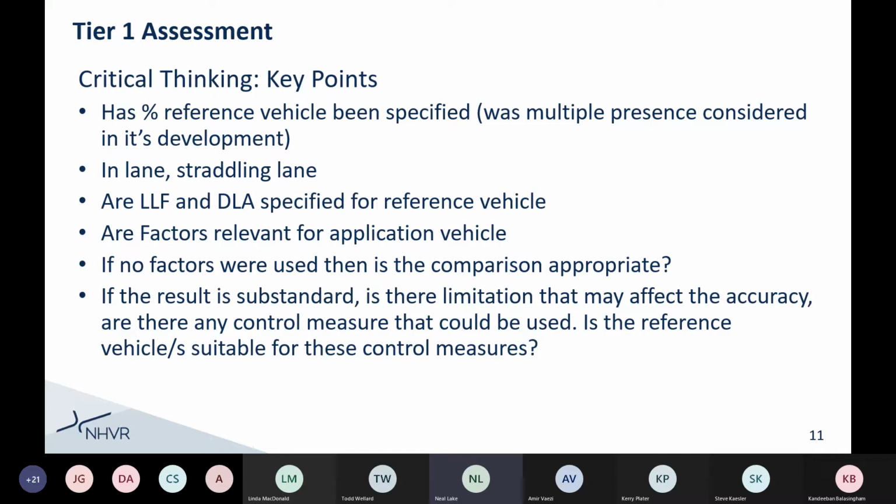could have a vehicle that has, the structure might have spare capacity. The rating factor might have come out to be, say, 1.25. And so the percentage of reference vehicle would be 125%. So you actually have more capacity than just the vehicle, but I think what we often see in assessments is people, suppliers may just look at it as a compliance assessment and go, oh, the bridge is okay for that vehicle. And it's important that, ideally whenever we can, we work out what percentage of vehicles are okay so that we can really maximize access to our networks.